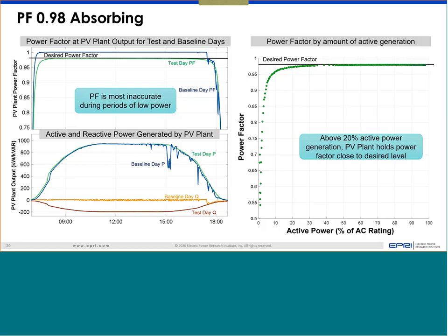Without knowing a little bit of details on how they are controlling the capacitor, that would be a good question. That is, is it always on, or is it actively managed based on what the plant is doing? Those will be the questions. Also, a capacitor may indicate a low voltage scenario, whether they are trying to fix that low voltage by having a fixed capacitor. I also heard the term smart capacitor, which is basically turned on and off depending on either voltage or VAR demand. So maybe you need a little bit more information on what the purpose is or how they're controlling the capacitor, if you know that information.